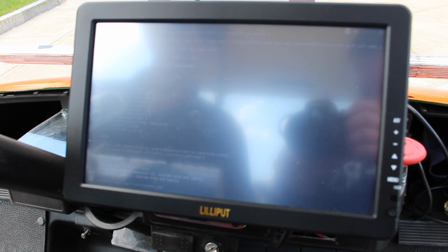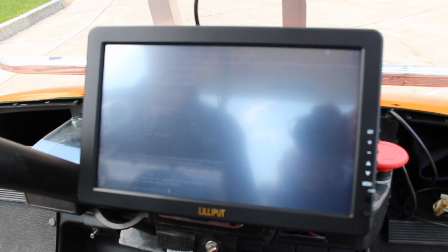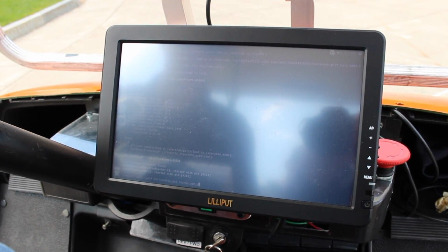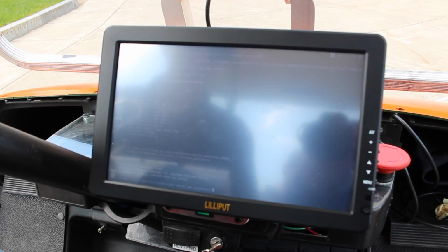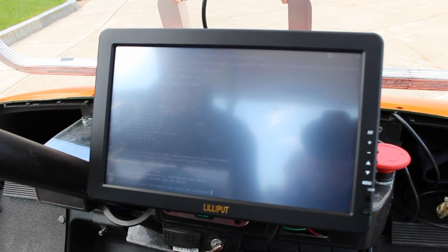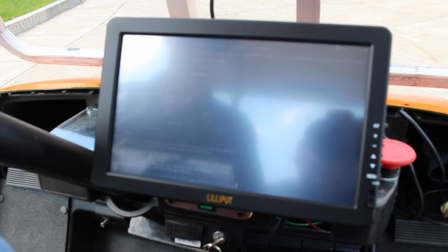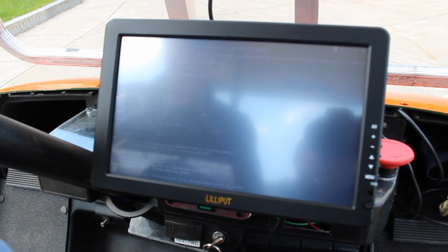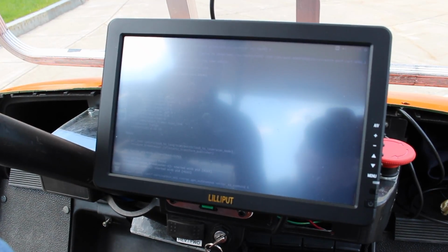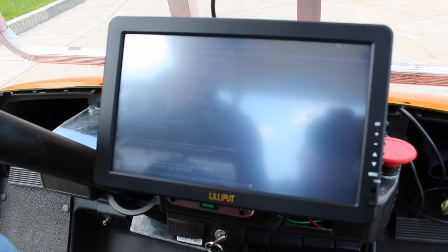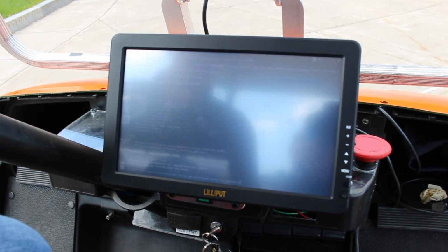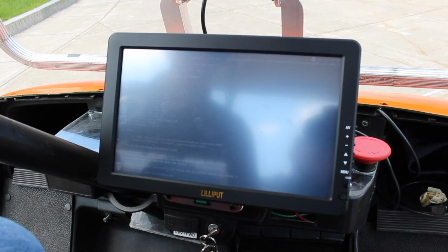And so now we're going to get the APM autonomous mode nodes running. The first one we're going to run is rosrun APM_autonomous, and that'll tab complete, and then vector_2_command. What this is going to do is take the desired vector and convert it into commands for the throttle, steering, and brake. And I'm going to background that.